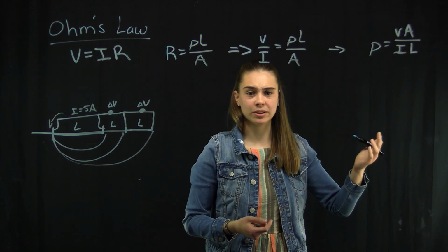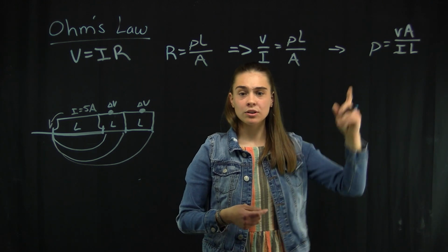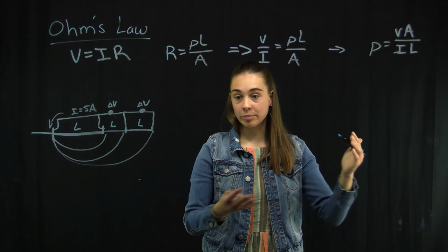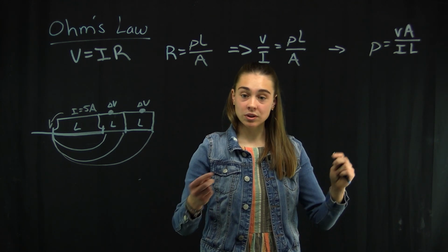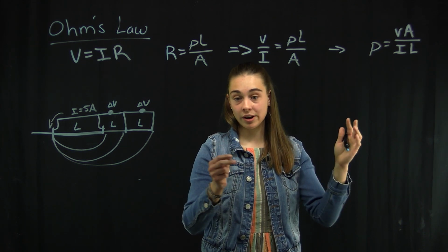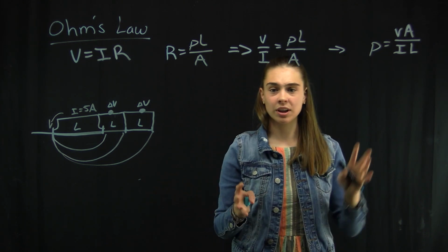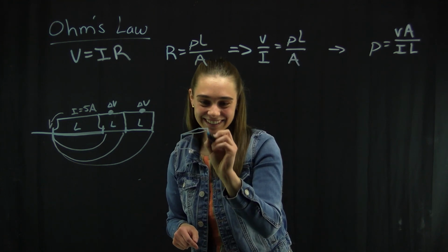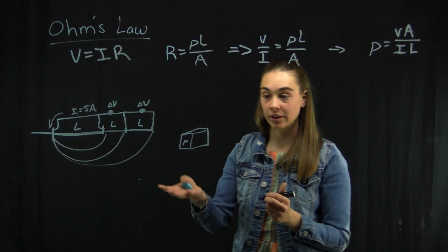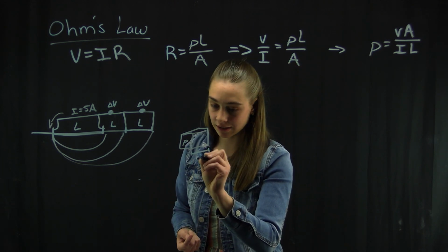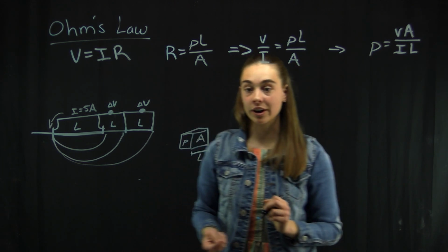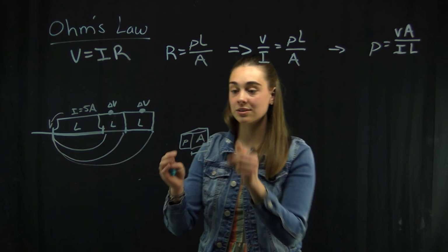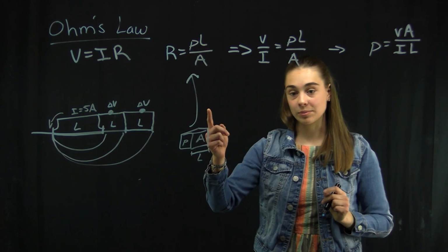have the rho equation where we know the voltage, we know the current that we're pumping into the ground, and we also know the distance, and we know the area. In a more simplified version, to really understand this equation, we can represent this ground equation as a box where we have the material's rho value, we know its length, and we have the cross-sectional area. So this is represented in a smaller form to find this resistance up here.